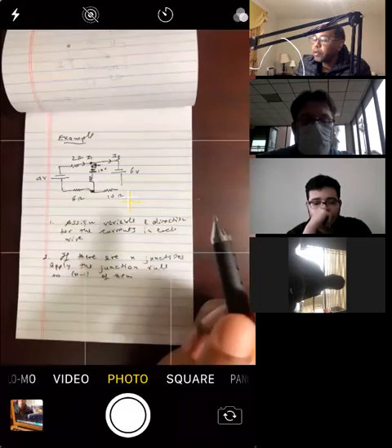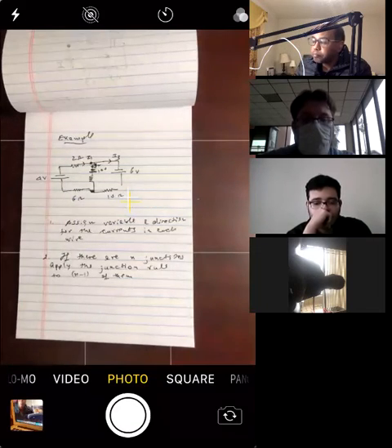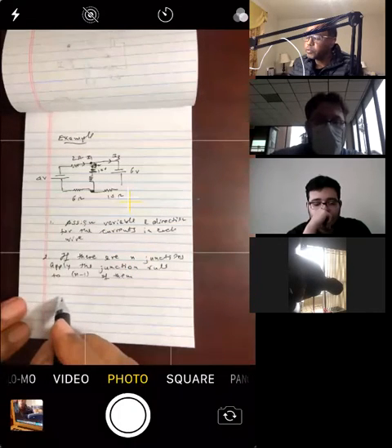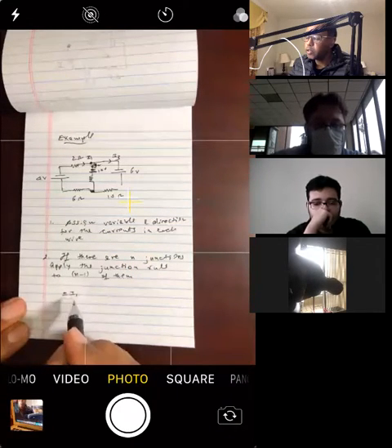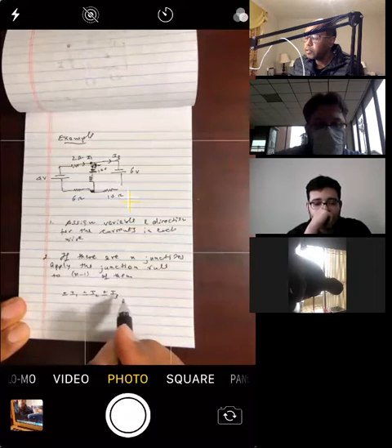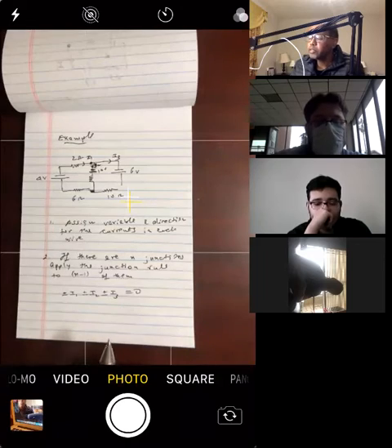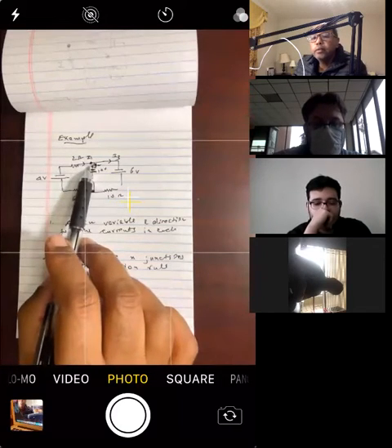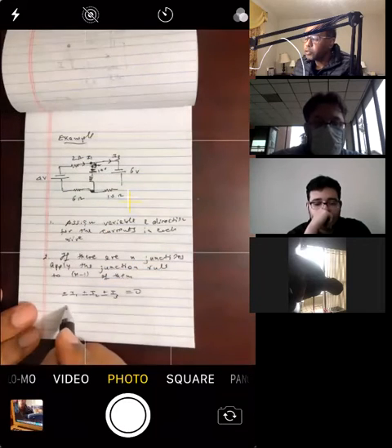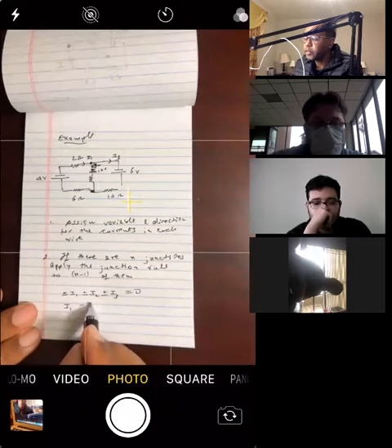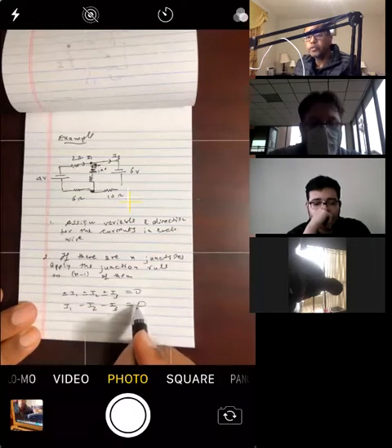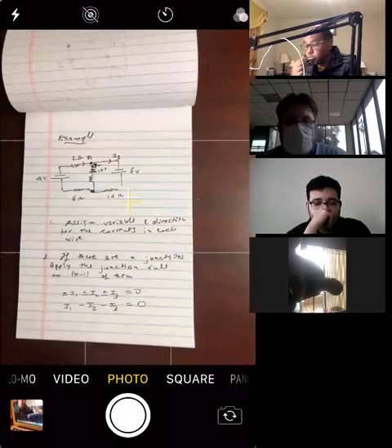All right. Okay. So let's do that. This junction. I have 3 currents. So this is my equation: plus or minus I1 plus or minus I2 plus or minus I3 equals 0. Right. Now let's pick the signs. If it is going in, it's positive. It's going out, it's negative. Okay. So I1 is positive, but I2 and I3 are negative. Okay, equals 0.